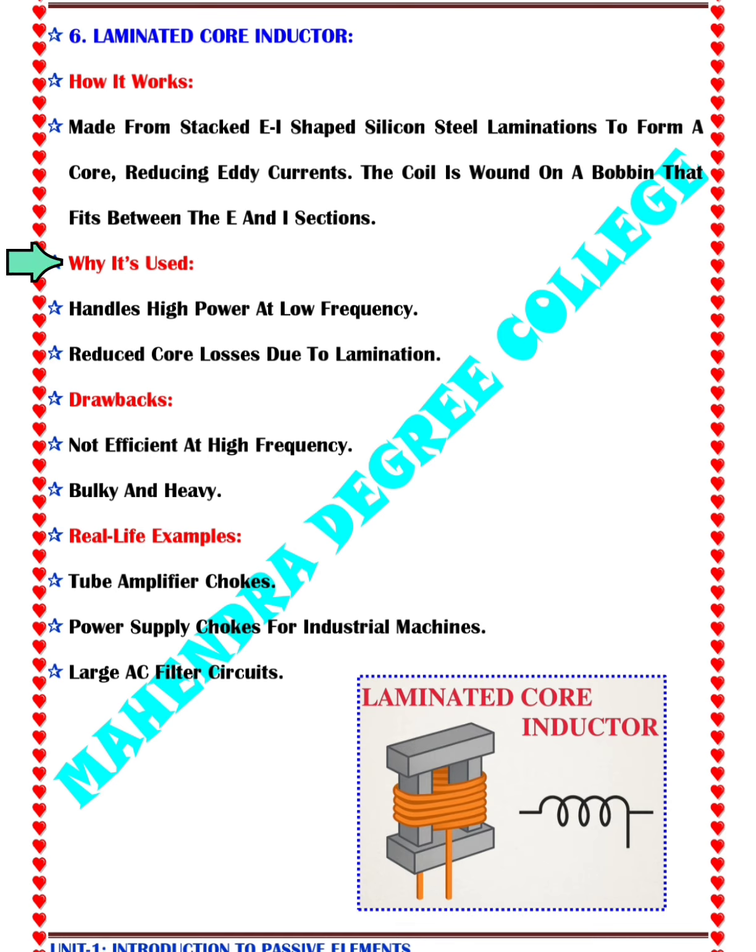Next, why it's used. Handles high power at low frequency. It means laminated cores can carry large currents and high magnetic flux without saturating easily. Suitable for low frequency applications like audio amplifiers or power transformers.